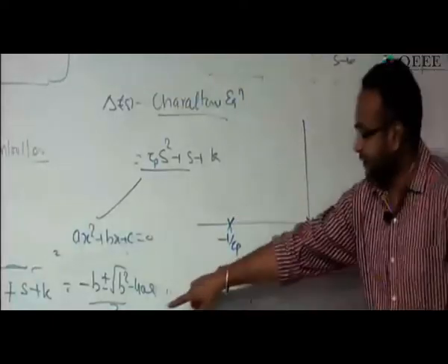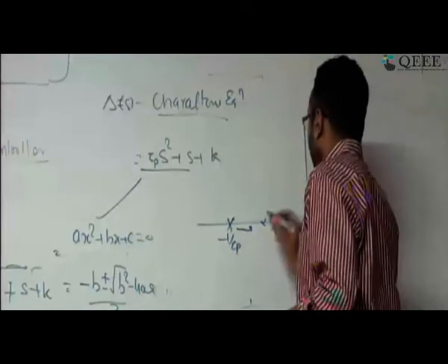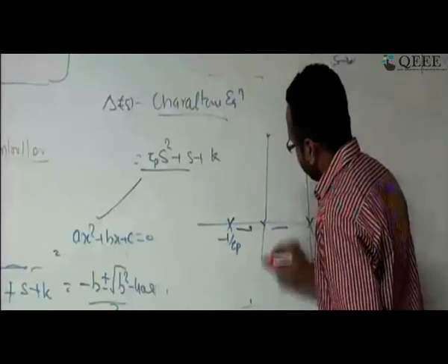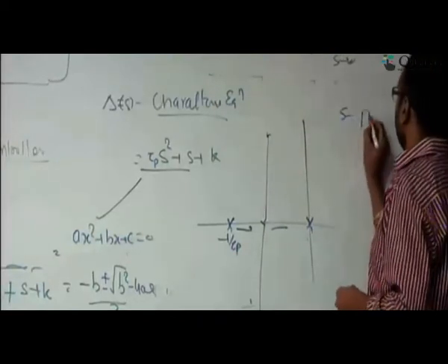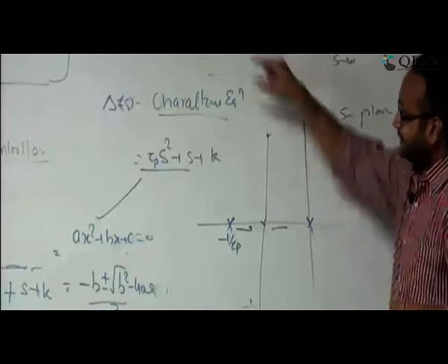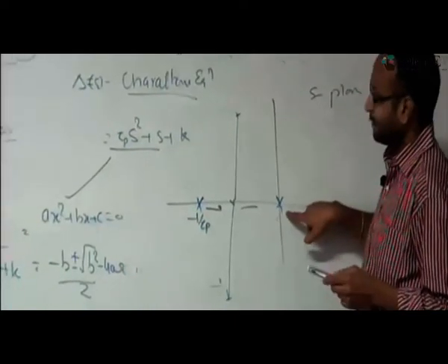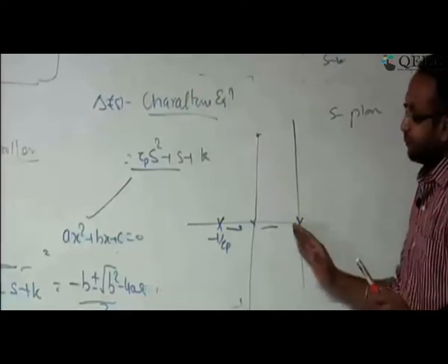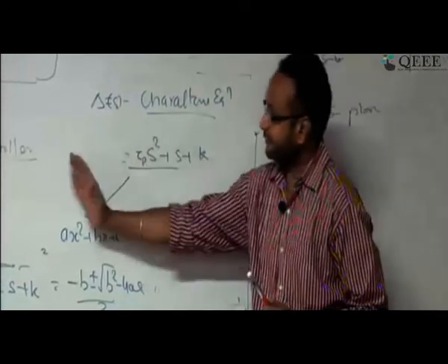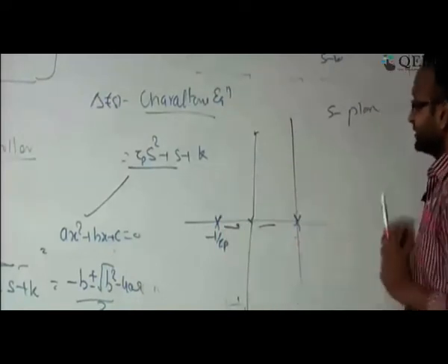Correct. Now if you keep increasing k, this is the asymptotic behavior, it will go to this side. Okay. So this is what I am talking about, the poles of the system. By adding an integral controller, what is happening? So tau p is your system pole and this is your 1 by s, you have got it. Now look at, as I mentioned, if my poles are very far away on the left hand side, system is fast.